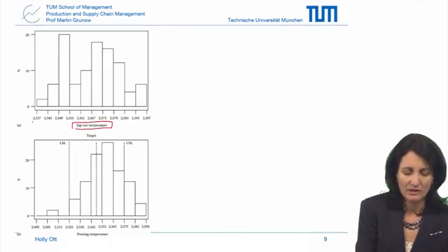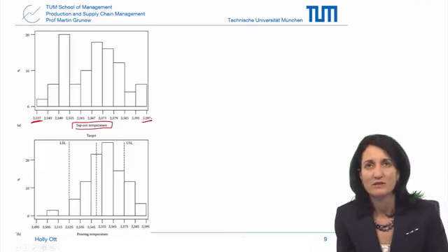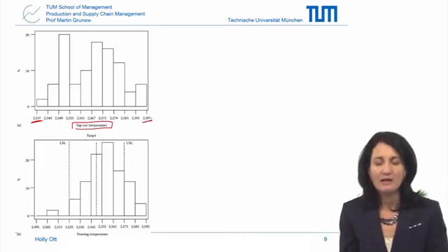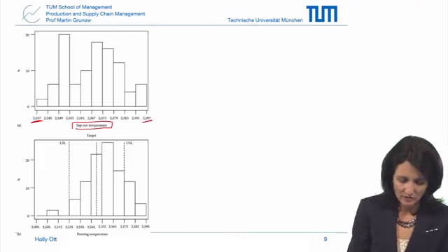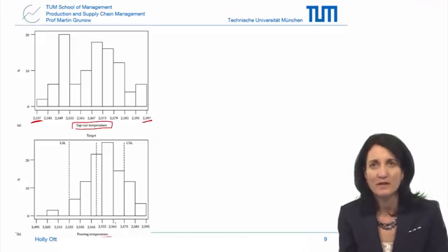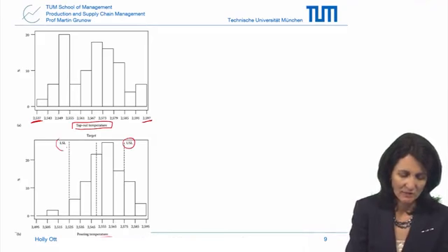So you can see this ranges from a high value of 2,537 degrees Fahrenheit to 2,597 degrees Fahrenheit. Then the molten metal is transported over to where it is poured, and we have the pouring temperature here. And here we have some specification limits.